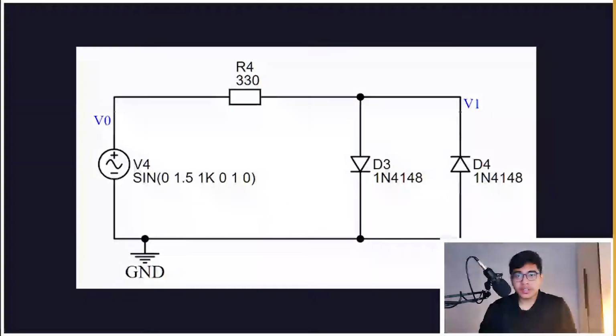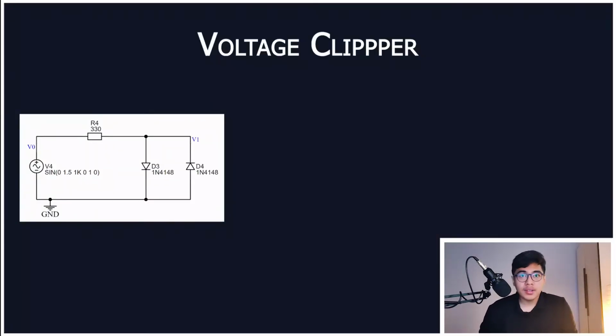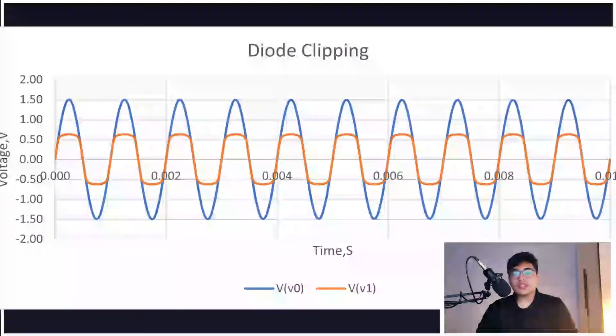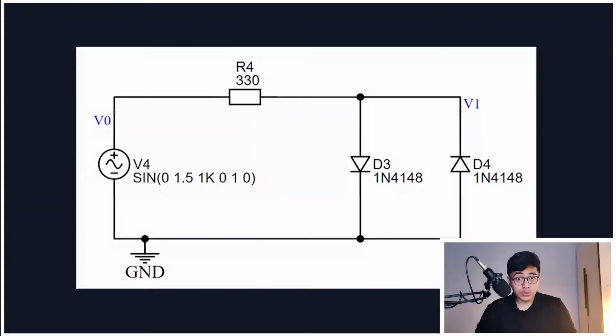When the circuit is built like the network right now, the output waveform will have its amplitude shrunk. This is called a voltage clipper circuit. This happens due to the resistor absorbing some of the current, which shrinks the output. The output amplitude is affected by the magnitude of resistance. Also, one thing to note, the output is in the same shape as the input waveform. It's because there are two diodes present. Voltage clippers are usually used for the separation of synchronization signals from the composite picture signals.